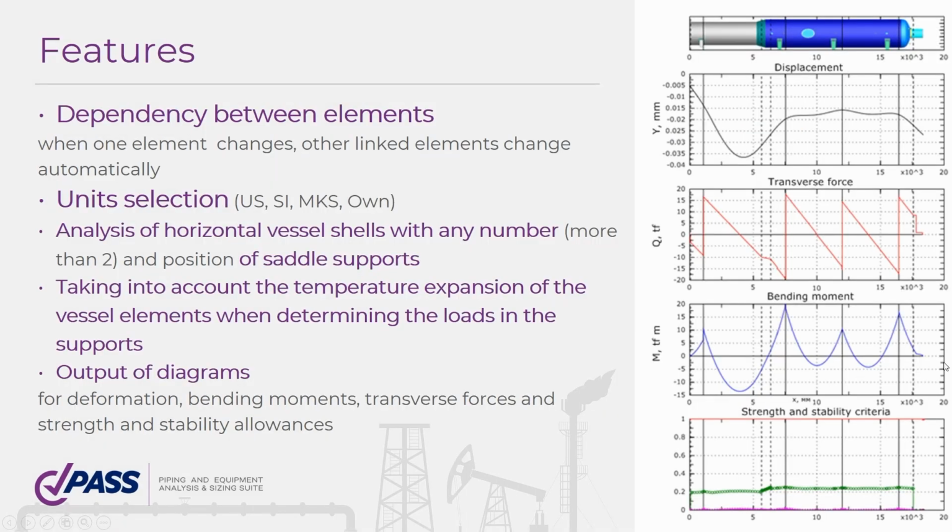Now let's look at calculation capabilities. If the diameter or pressure in one element changes, after a warning, the program will change these values in adjacent elements. The user can select any system of units: international, imperial, or customary. Temperature deformations can be taken into account in the calculations, which is especially important when determining the loads on supports and foundation. The diagrams in the report allow you to see deformation, bending moments, transverse forces, as well as the safety factor for strength and stability.